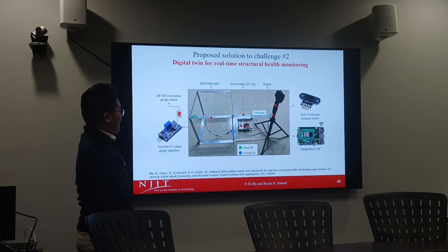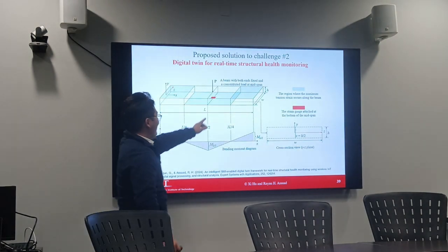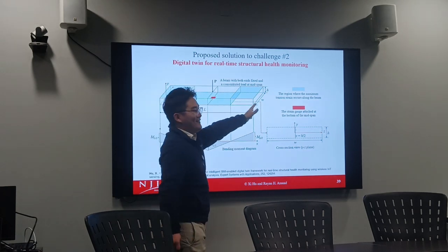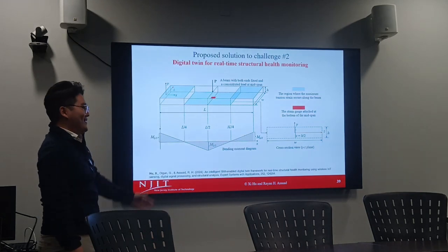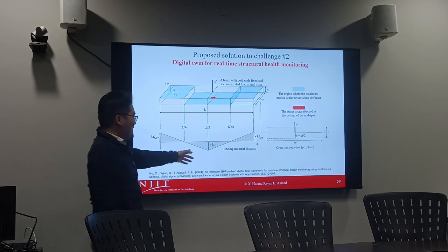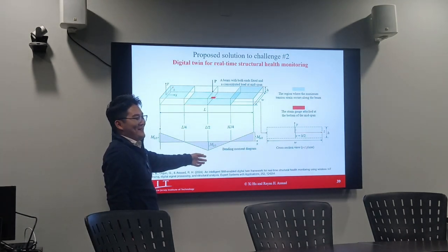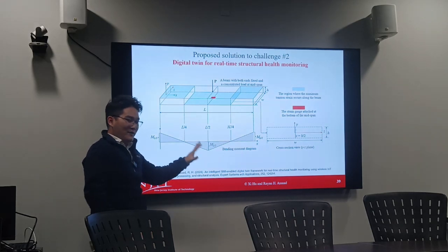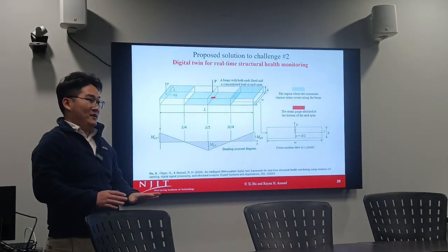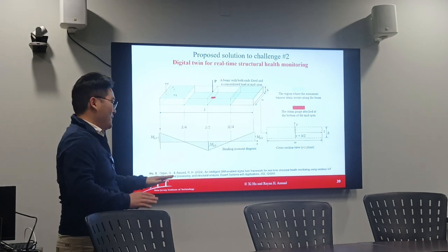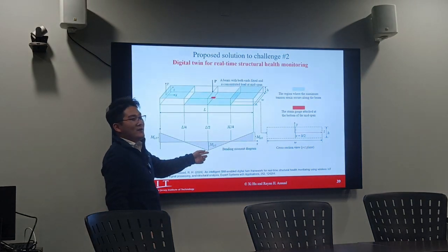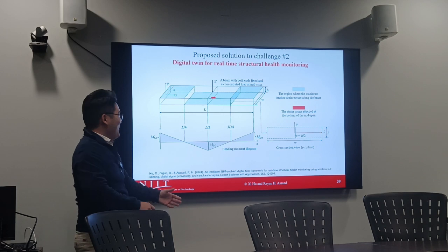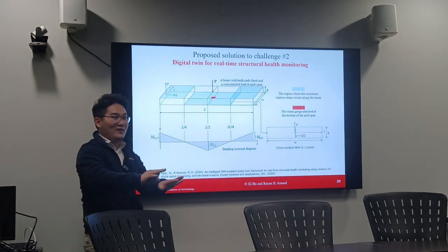That's a very good question, right? And I mentioned using one measurement to capture the structural behavior of the entire beam or column. This is how we did it. We use a bending moment diagram, which is very familiar, right? But we have to guarantee that we're not going to permanently deform this column or beam. If you deform it, this doesn't work. It's going to be within the elasticity region. That works. Once we know that it reached there, we know we cannot do more. It's very close.